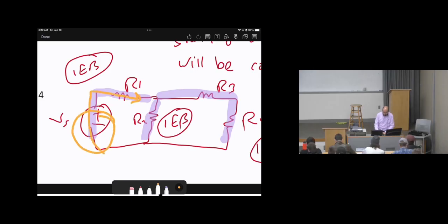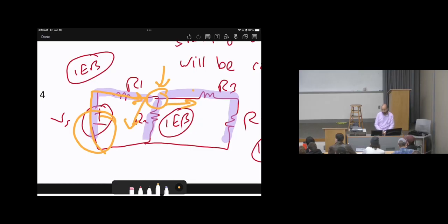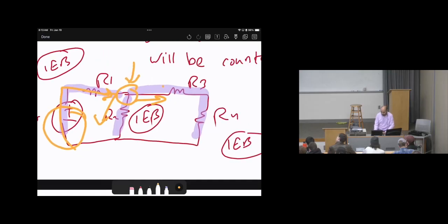The water will not split, right? This means they are sharing the same current. While at this point, the water will split here and split here. Therefore, these elements will share different currents. Then with R3 and R4, if water is flowing from R3 toward R4, it will not split, therefore they are sharing the same current.